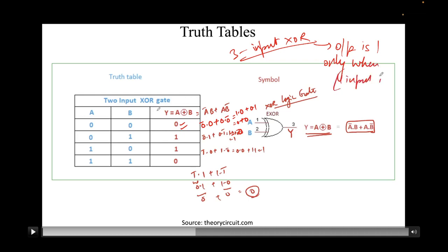So please remember that. It is exclusive in that sense. If some time comes, maybe I'll show you the truth table for a 3 input XOR gate. But for now, I just wanted to point out that an odd number of inputs have to be 1. That's the idea. So if one input is 1 or 3 inputs are 1, then you will get the output 1 from the exclusive OR gate. Yeah, so let's move forward.